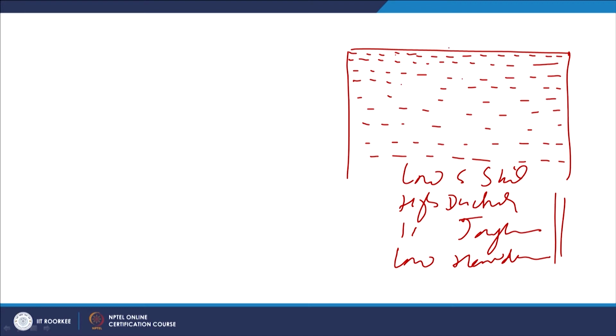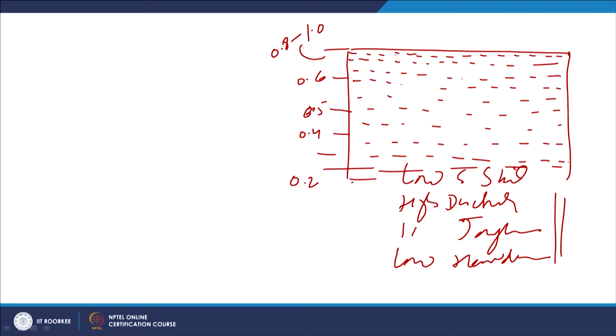On the other hand, near the surface layers we may have like 0.8 to 1% carbon, while in the subsurface region it will be gradually decreasing like 0.6% here, 0.5% here, 0.4% here, and gradually it will reach 0.25%, as per the carbon concentration in the substrate.